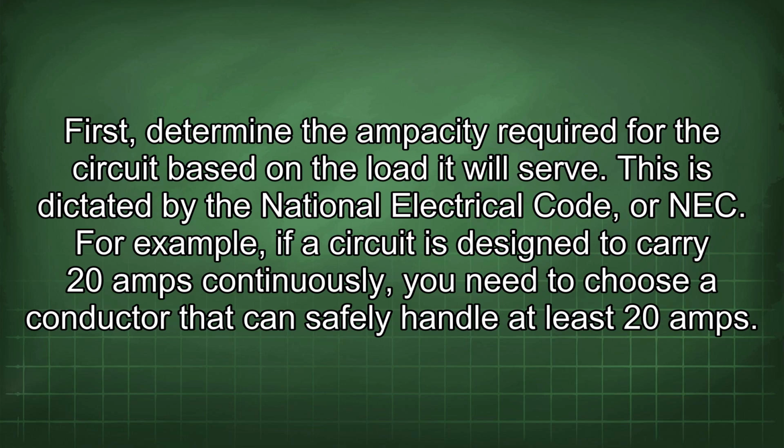First, determine the ampacity required for the circuit based on the load it will serve. This is dictated by the National Electrical Code, or NEC. For example, if a circuit is designed to carry 20 amps continuously, you need to choose a conductor that can safely handle at least 20 amps.